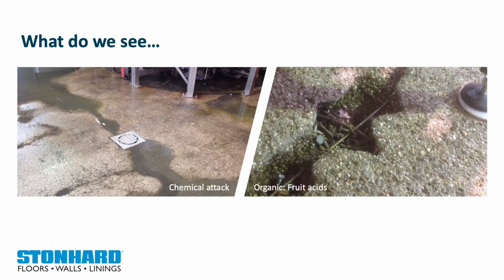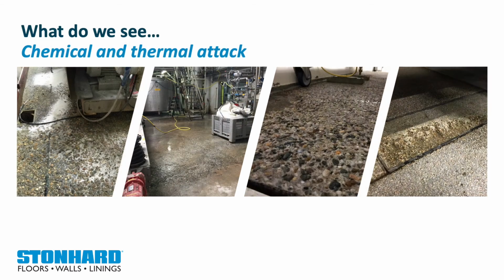These fruit juices damage the unprotected concrete floors for several centimeters deep. Some cementitious-based flooring systems are only suited for cleaning temperatures up to 50 degrees Celsius. They wear off or damage because of the chemicals and the temperature, or even the organic acids that come from the food that is produced.